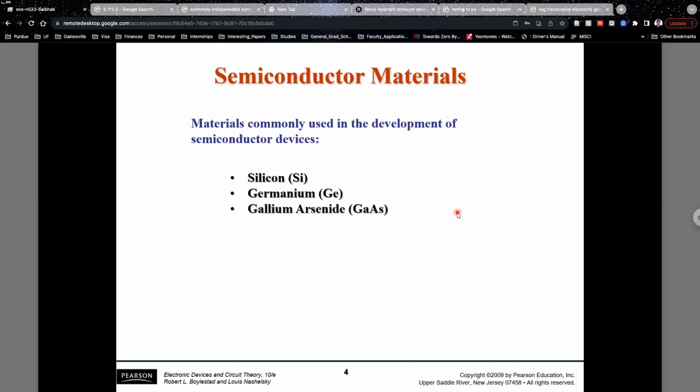Why would you call it a p-type semiconductor? Because you have absence of one electron in the entire structure. If you had all the electrons in the structure, you know from the atomic properties that the number of electrons will be same as the number of protons in the atom, and that's why the atom is neutral, electrically neutral. So number of electrons will always be same as the number of protons in the individual atoms. But if you look into the entire structure, here you have a silicon which cannot bond on the left hand side, because on the left hand side it does not have a silicon, it has a boron atom.